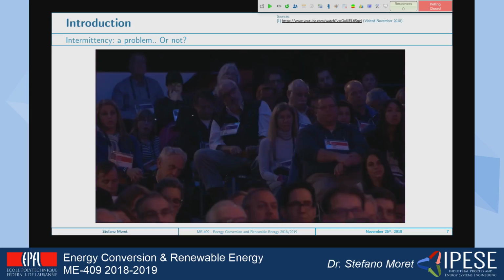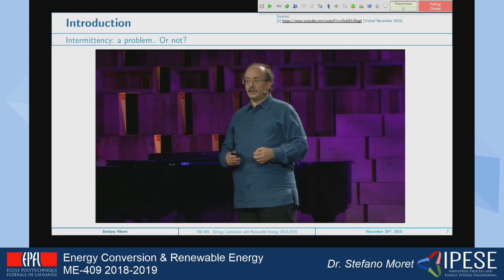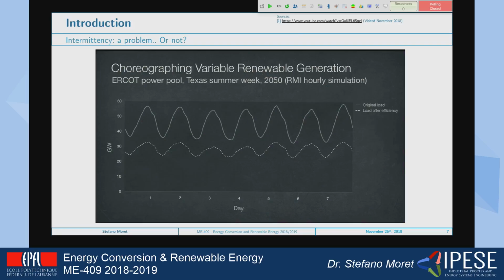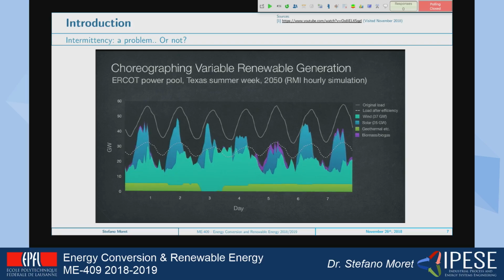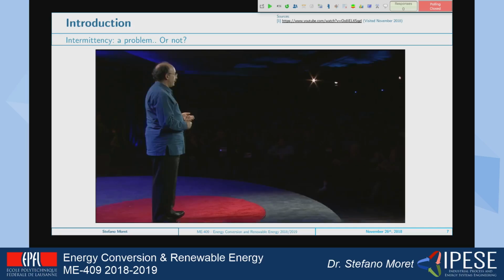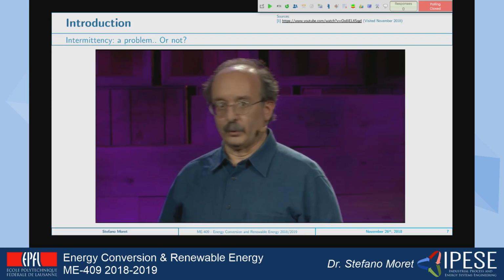For example, the isolated Texas grid's summer electric loads can get much smaller and less peaky with more efficient use, profitably. Now, combining 86% wind and solar power with 14% other dispatchable renewables creates surpluses that can charge up ice storage, air conditioners, and electric cars. And then recovering that distributed storage when needed and filling the last gaps with unobtrusively flexible demand can then deliver 100% renewable electricity every hour of the year with only 5% left over.